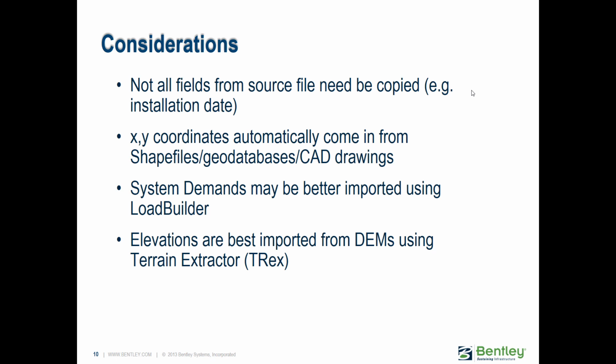Most of the time, demand data usually takes the form of customer meter information or some type of geospatial information, like shapefiles of the customer element, customer meters, or in some cases you have just some area-based data, like maybe you have polygon areas of different land use types or different population types, and maybe in one type of population the average demand is some flow value per person per area.